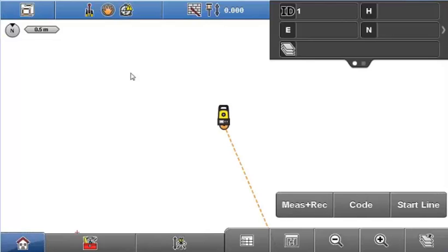So you might have a wall from a building that's adjoining your site or adjoining your lot, so you know that that building is going to stay there. You might have a road, like I showed you in my sketch before, that you can measure 2 points off and you know for sure that that road is going to stay. So that way you can always position yourself locally, and it's what a foreman tends to use a lot. And as I said, it gives you then the 2D coordinates.